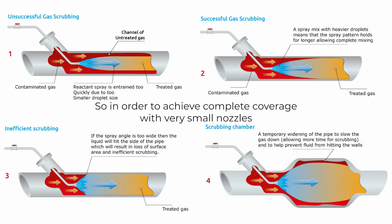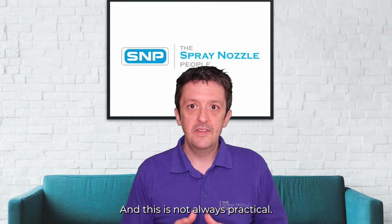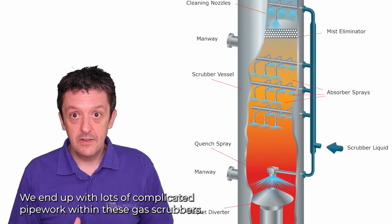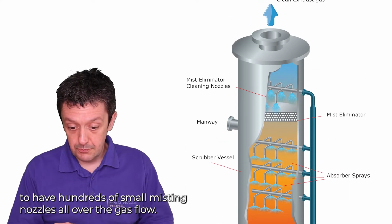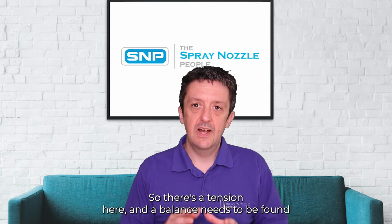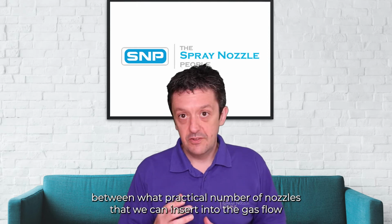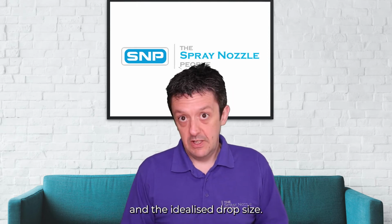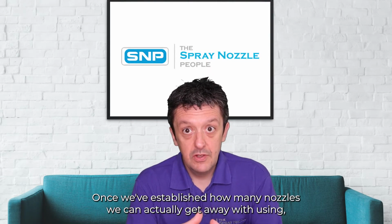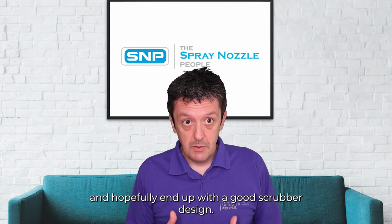So in order to achieve complete coverage with very small nozzles and small drop sizes, we need more and more of them. This is not always practical. We end up with lots of complicated pipe work within these gas scrubbers, and it's just not possible to have hundreds of small misting nozzles all over the gas flow. So there's a tension here, and a balance needs to be found between what practical number of nozzles we can insert into the gas flow and the idealized drop size. Once we've established how many nozzles we can actually get away with using at what drop size, we can then map those around the gas chamber and hopefully end up with a good scrubber design.